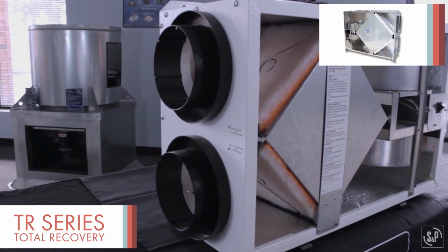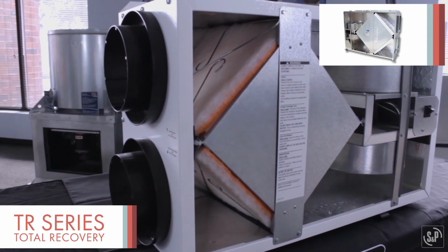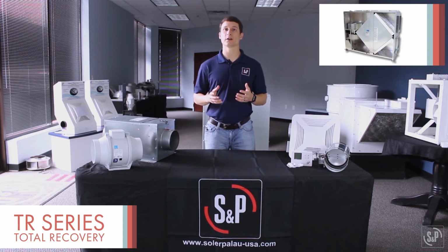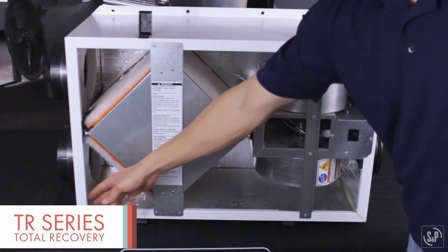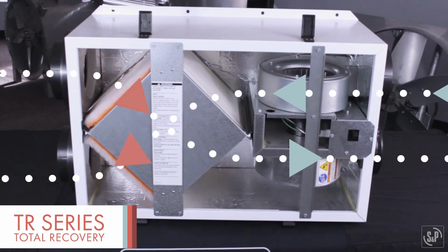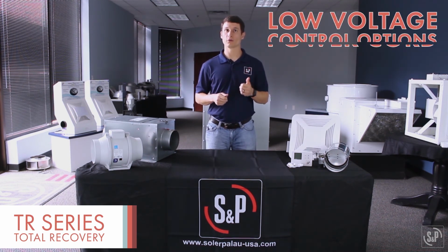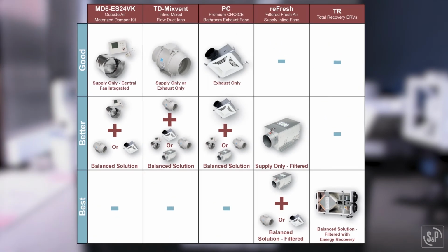The S&P TR series is the best outside air solution available. Use the TR line of high-quality ERVs to simultaneously supply and exhaust equal amounts of air to the home as a balanced filtered solution. The two air streams never touch, but they pass through a high-efficiency core that transfers heat and humidity from one stream to the other. This recovers some of the energy that would normally just be wasted with a typical supply or exhaust fan. There are 4 models available with standard galvanized steel housing, MERV 8 filter, power cord, and low voltage control options. The TR series is the ultimate combo system to provide fresh air.